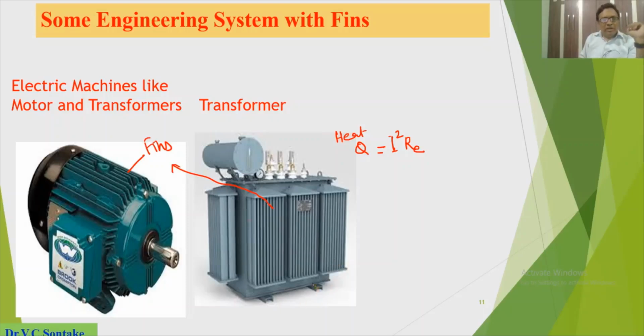And we can also see the heat transfer rate from the transformer surface to the air is by free convection. No mechanical agency is employed. So here fins are the only option to enhance heat transfer rate and to keep the temperature within a safe, optimum limit.